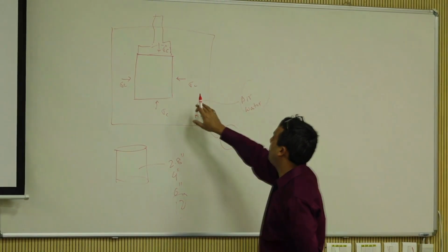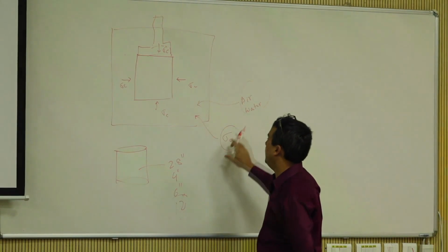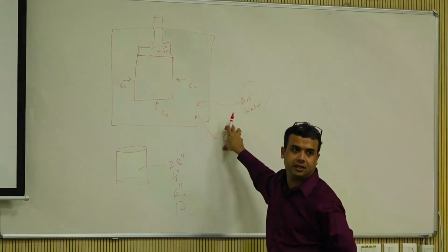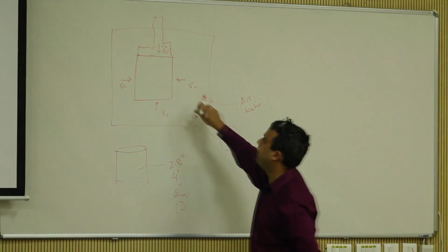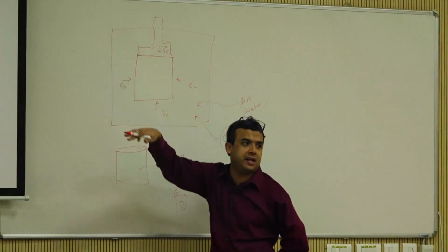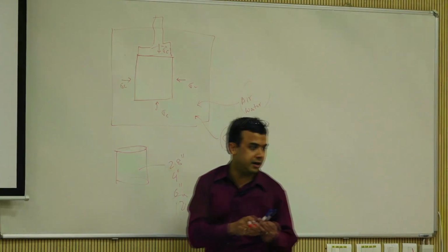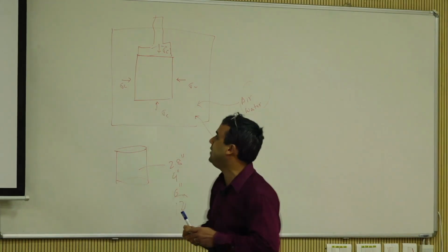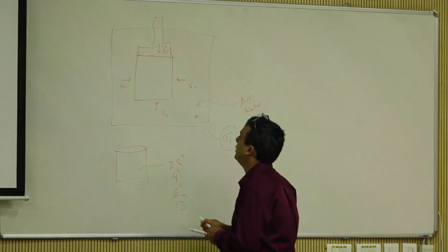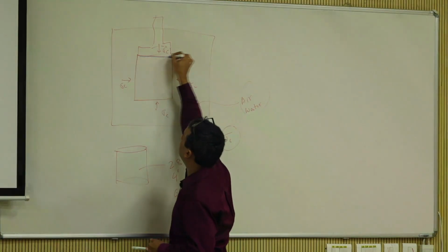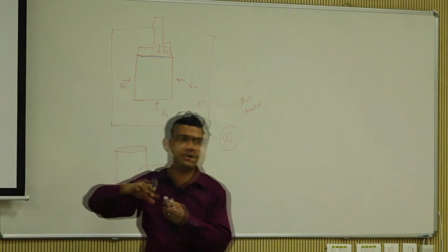So you're pressurizing the system, and you're applying what is known as confining pressure, and then you apply what is known as the mechanically induced deviator stress, and we call it deviator because that is the deviation from its standard state.